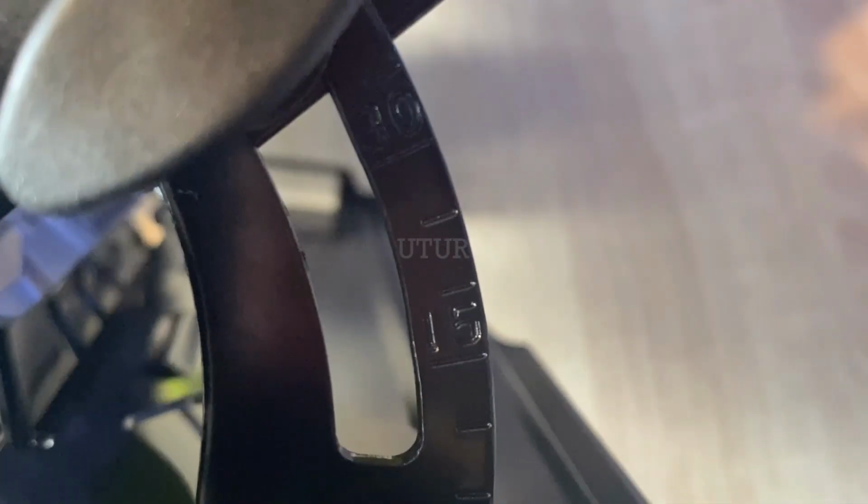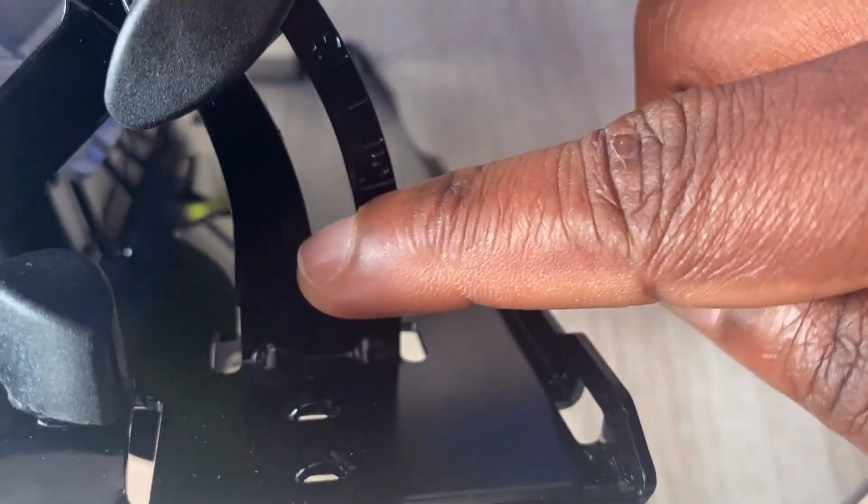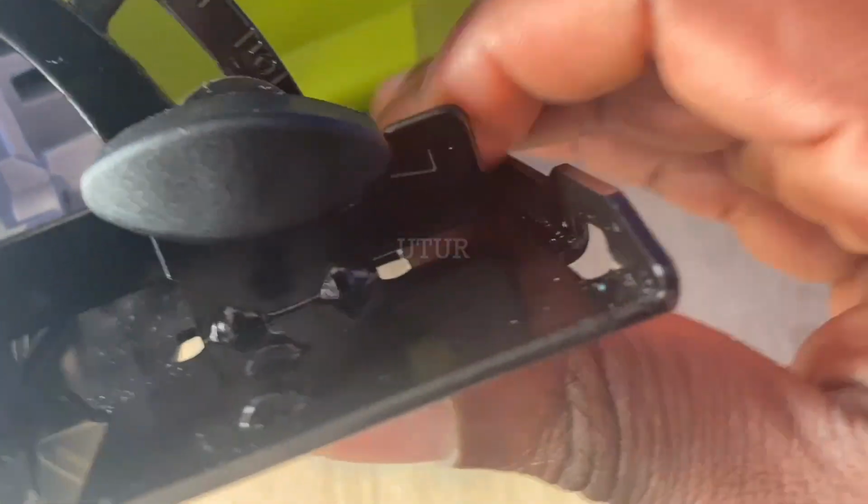Here, the bevel cut is set at 45 degrees, and you can see that the base plate is tilted away from the tool. Suffice to say, the bevel cut capacity is anywhere between 0 to 45 degrees. You can cut 0 degrees, 15 degrees, 30 degrees, and 45 degrees on the bevel, okay? So basically just undo the bevel lock anti-clockwise, toggle through the angles that meet your bespoke requirements, then turn the bevel lock clockwise to secure or confirm the angle that you want to cut through.